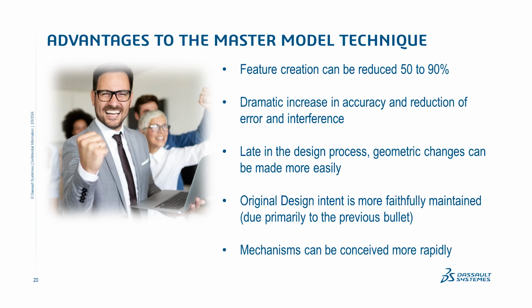And you can clearly design the intent with offsets and whatever in the master, so that there's never any interference, and all of the design intent is being driven from a single part file, instead of having multiple part files with their independent features that are being driven independently. And that really can easily lead to interference between parts.